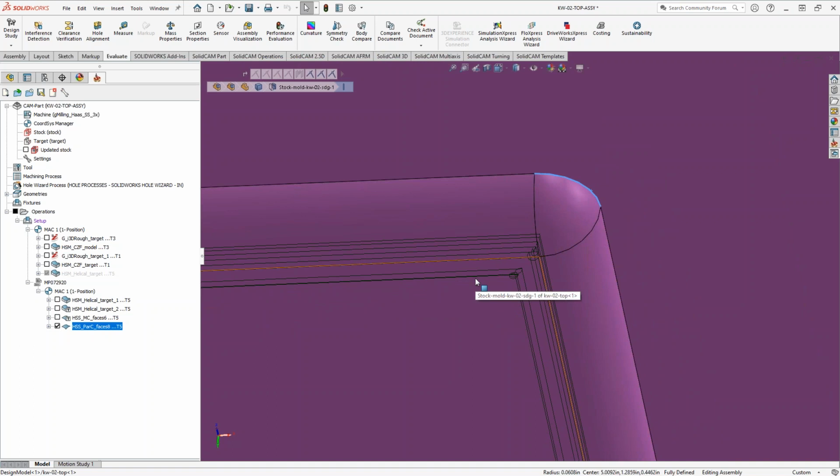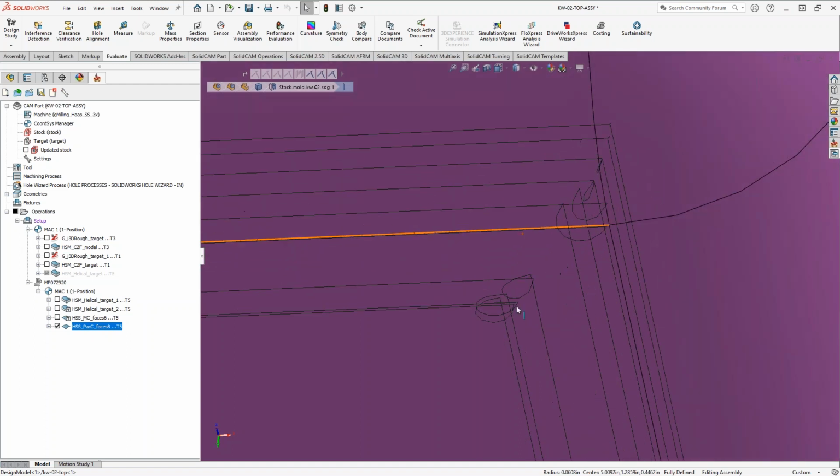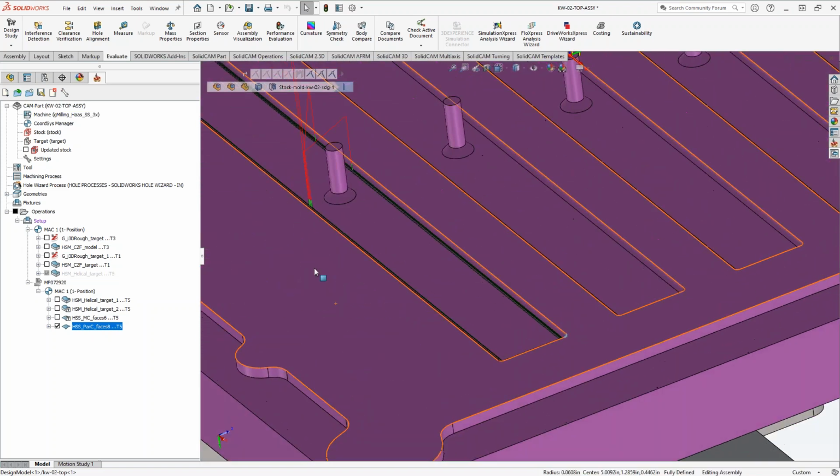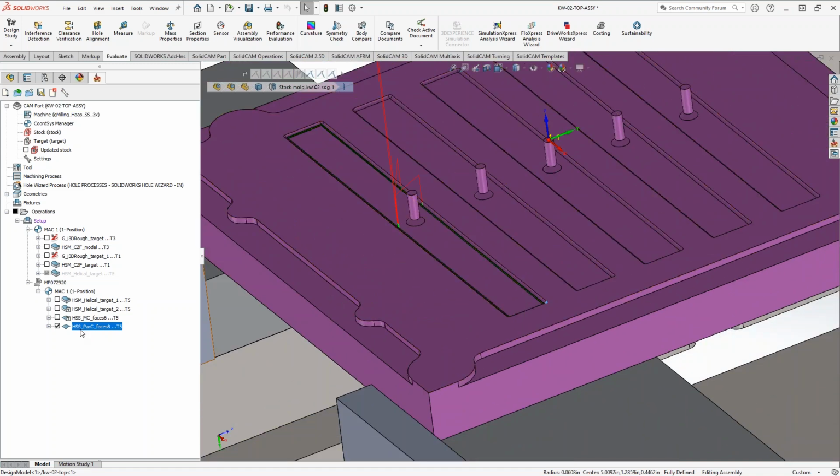So the difference between HSM and HSS is pretty visual right there. HSM just went in there with whatever arcs it could fit, and that's it. With HSS, it's trying to get very specific, trying to clean that up as much as possible, especially with the shape of my tool. But you can see it's generating some weird movements there just to get that done. But I was able to do the same sort of thing in 2 toolpaths with some extra clicks. And sometimes this is what you would have to do, because your HSM toolpath would be trying to do everything of the solid in one go, and sometimes that's not going to work. You can't really apply one strategy, one technology to an overall solid or to a limited area like that.